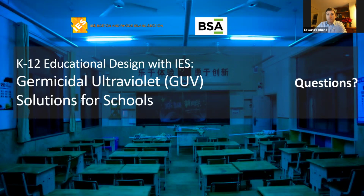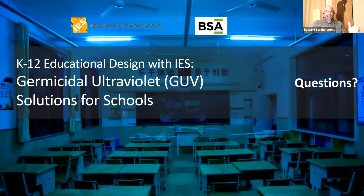I want to go back to the previous question regarding reflectance. I'm not sure if you were also mentioning space reflectance, but it is critical in upper air applications that the ceiling reflectance be reduced. Unlike lighting, where we want higher reflectivity within the ceiling, for UVGI we do not want that irradiation to reflect back onto the occupants during occupied times. So absolutely, it's critical that you coordinate your ceiling reflectance with that solution and aim for a lower reflectance for the ceiling.